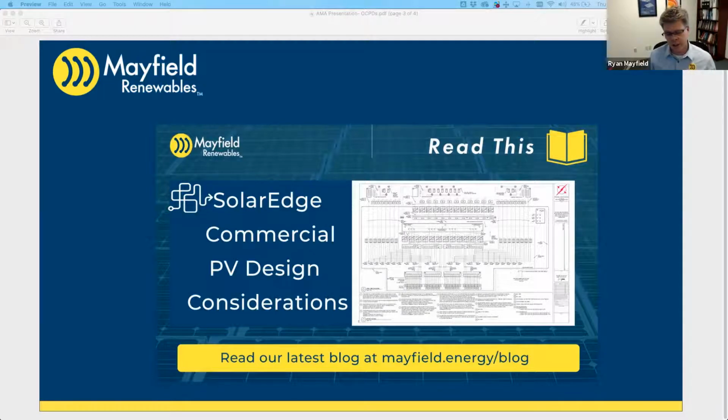This new 705.11 makes it easier, I would say, to install supply side connections, because now we actually have some real rules, as opposed to 2014 and before. The supply side connection part of the code just basically said, yeah, you can do it, but it didn't tell us how to do it. And then there's another section, and I remember I asked you about this the other day.